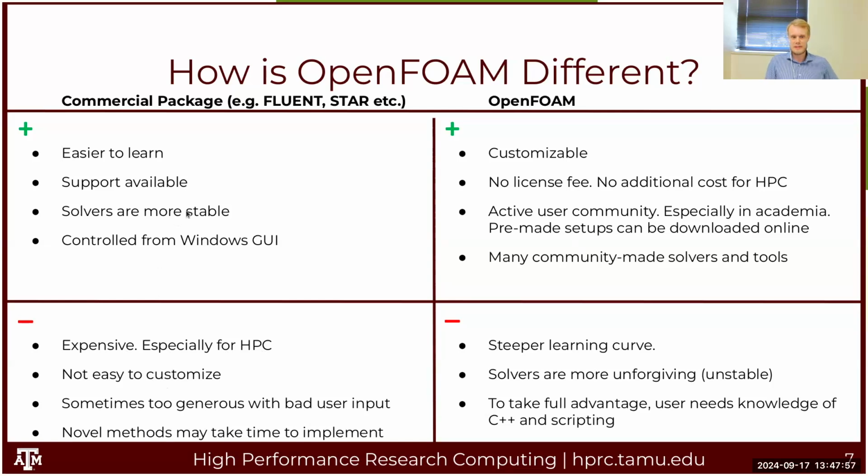I said that it's a plus that the solvers are more stable, but sometimes that is a bad thing, because when you purchase one of these commercial packages, when you spend the money, you expect to get some results out of it, which means that sometimes they've added a little bit too much generosity in having things converging when they probably shouldn't have converged, which doesn't rhyme very well with the garbage in, garbage out philosophy. In commercial packages, you can sometimes have garbage in and pretty pictures out, which can be a little bit dangerous.